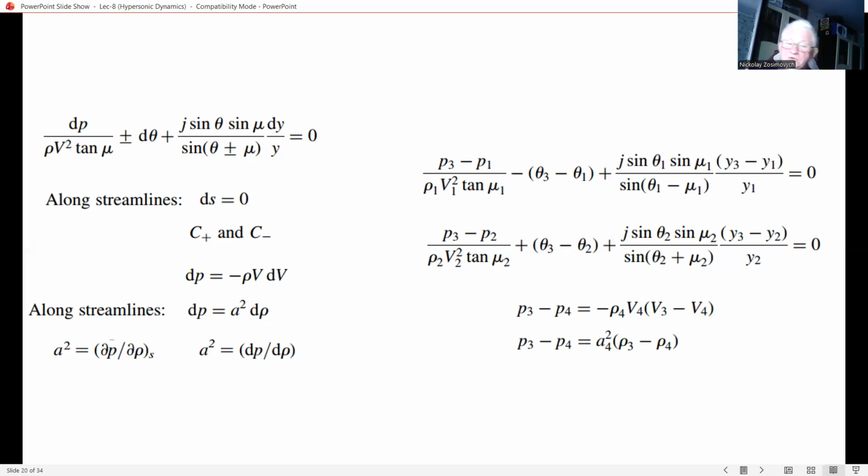The preceding unit process is carried out from point to point in a sequential fashion, marching downstream from the initial data line. Slight modifications to the unit process are made to satisfy the boundary conditions at the shock wave and the body. In this fashion, the complete inviscid flow field between the body and the shock wave can be numerically constructed. And again, emphasis is made that this is an exact solution.